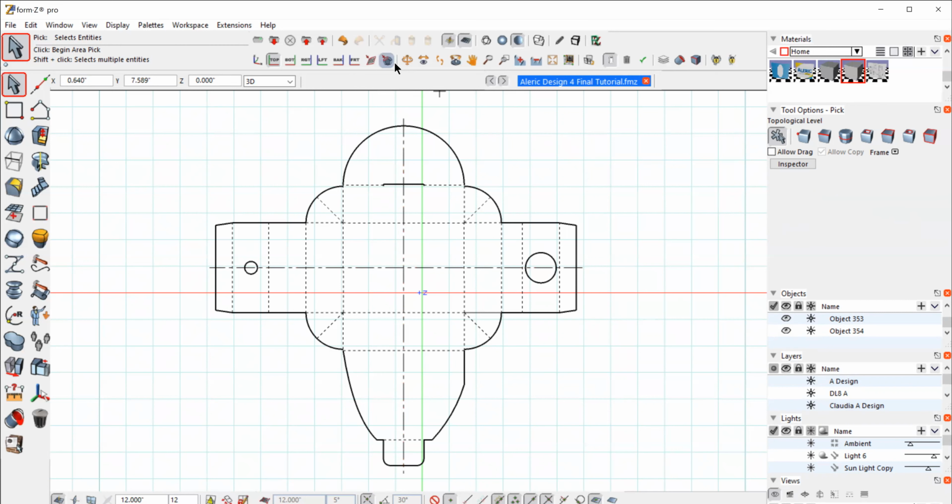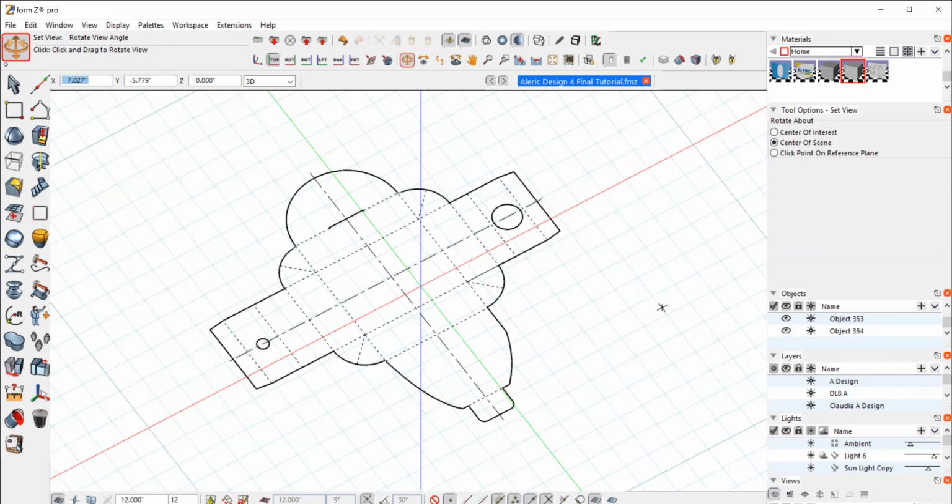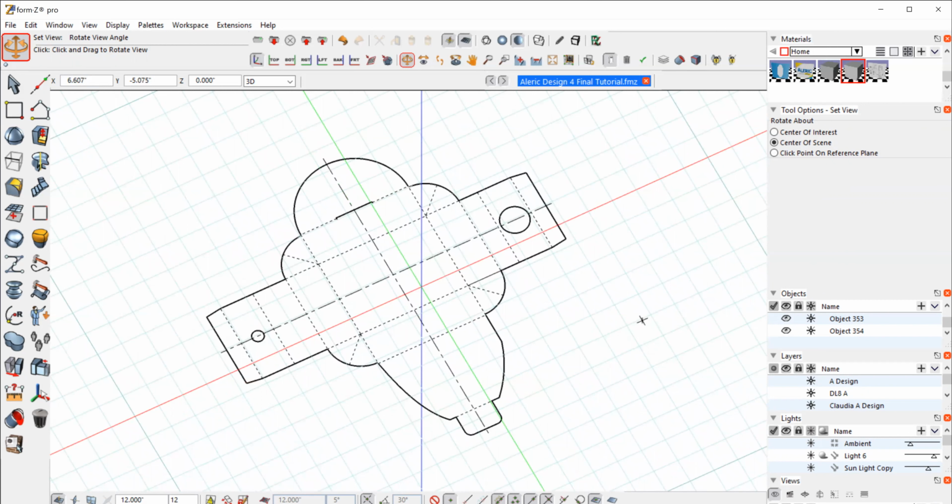Okay, so this is my line weights. And the only way I could do that was to separate all those, so I can keep that separate. And it's also beneficial to separate all those when we export into other formats. We can't export directly into Illustrator, but we can export as a DXF. DXF reads 3D data from the top view only, so don't draw your die line from the front view. And if you export it as a DXF, you'll just get one big line because it's looking at it from the top view. So you always look at it from the top view when you do it in 3D. So when you save out a DXF and bring it into Illustrator, it will read it. For this exercise, we're just going to export this as a JPEG. So we have a nice clear image of what our die line looks like.